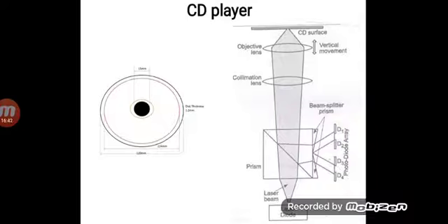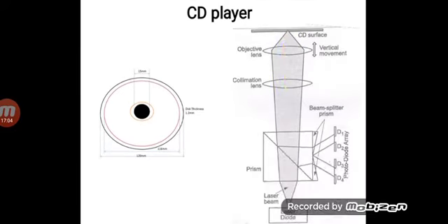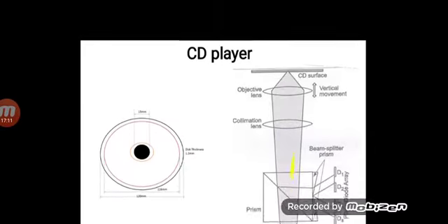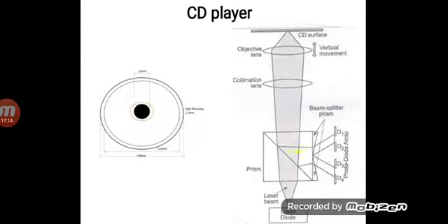So what we do is use another laser beam which is meant to focus on the compact disc while the disc is rotating, and we use a half silvered mirror or a prism structure, where from this side the laser beam can pass and hit the CD surface, but when the laser beam is reflected back from the CD material, it will not penetrate and go back to the laser beam assembly; rather it will be deflected towards these photodiode arrays.